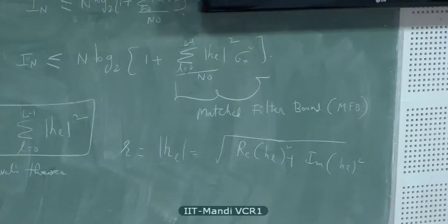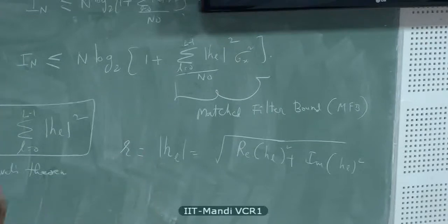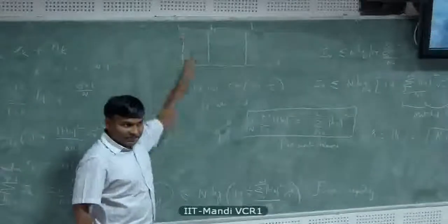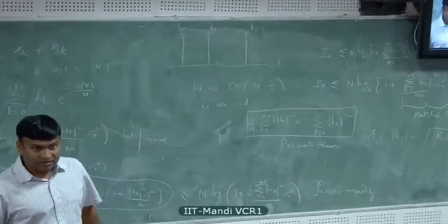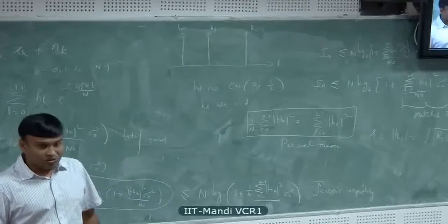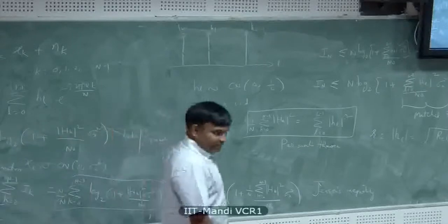Okay. The Rayleigh random variable, the envelope, goes through deep fades. You send a symbol, this has probably some 1 over L energy, the variance, but the envelope takes very low values very frequently. So the receiver suffers from what is called fading.